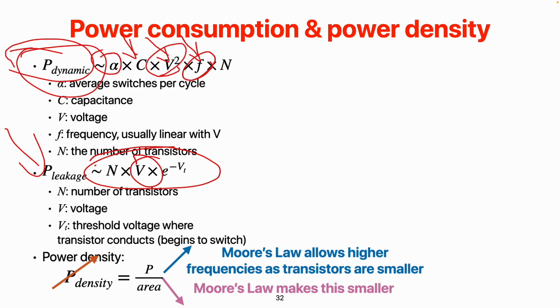So the most effective way to reduce power consumption is to lower the voltage, but that comes with the cost that you also have to lower your frequency. And the other thing is that you cannot indefinitely lower your voltage, because if you have some electrical engineering background, you would know that to judge if the content within a transistor is 1 or 0, you need a clear threshold voltage that allows us to judge that. So you can never lower your voltage below that. Otherwise, everything will just be treated as 0.